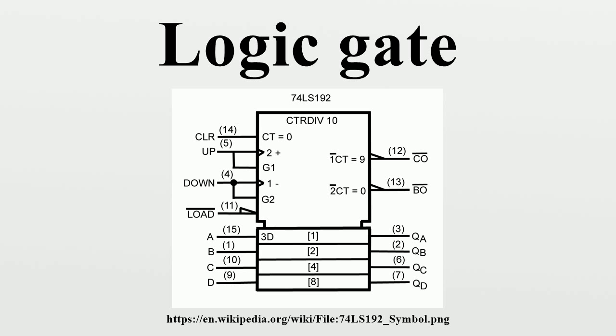Three-state logic gates. A three-state logic gate is a type of logic gate that can have three different outputs: high, low and high impedance. The high impedance state plays no role in the logic, which is strictly binary. These devices are used on buses of the CPU to allow multiple chips to send data. A group of three states driving a line with a suitable control circuit is basically equivalent to a multiplexer, which may be physically distributed over separate devices or plug-in cards.